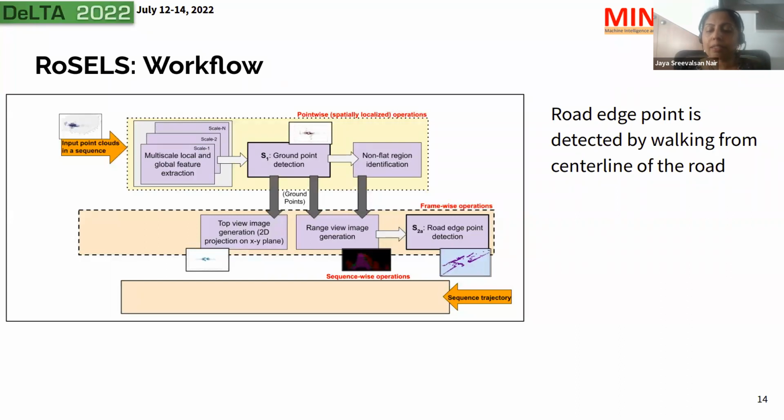These points are thus the closest to the medial axis of the road, or in simple terms, the center line of the road. Thus, we take the range image. In the range image, we walk along each row, and the curve points which are closest to the center line are retained, the others are thrown away. We do this for the right bank and the left bank of the road, and for the front of the vehicle as well as the back of the vehicle.